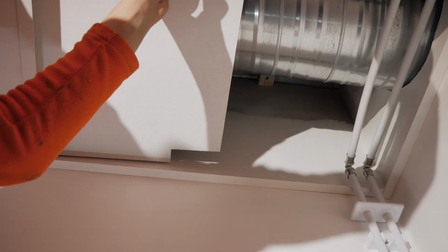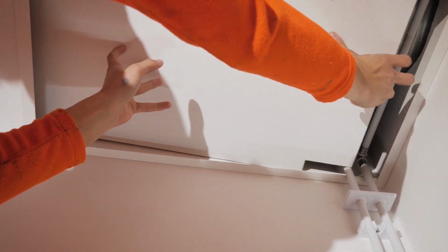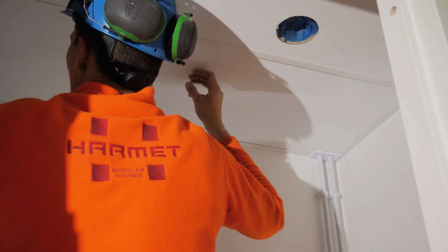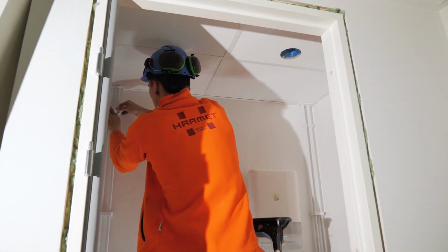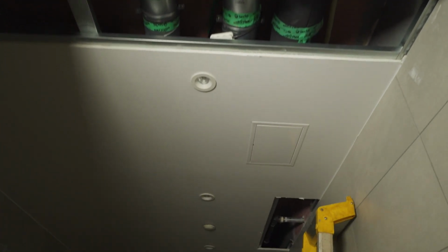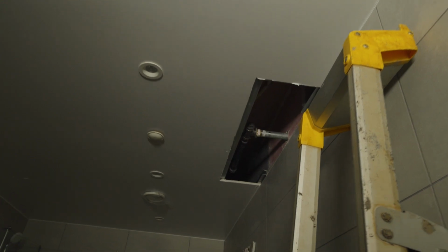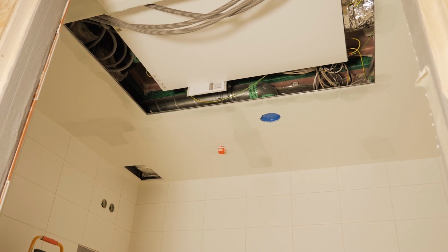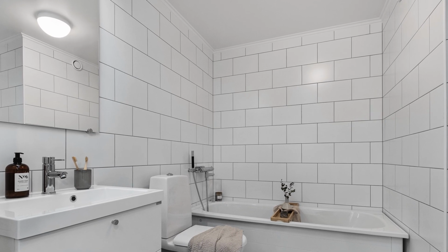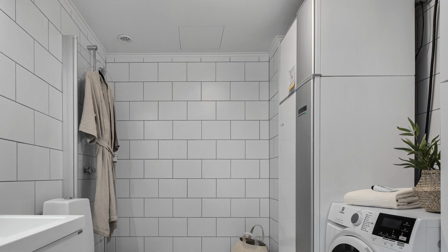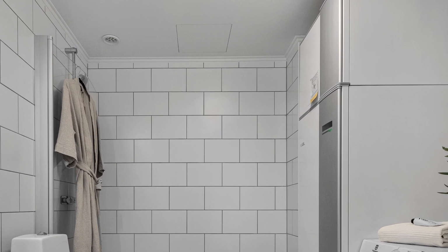The ceiling in a wet room, however, has a different solution, as it generally consists of two parts: the main ceiling and a suspended ceiling. The main ceiling behind the suspended ceiling is covered with moisture proofing. Ventilation ductwork and electric cables are also attached here. In the case of small living spaces, a ventilation unit as well. The suspended ceiling, which covers the technical utilities, is generally made of mineral wool or compressed wood-based boards, moisture-resistant plasterboards, or other similar decorative materials. If necessary, an access hatch is installed in the suspended ceiling for access to technical equipment.